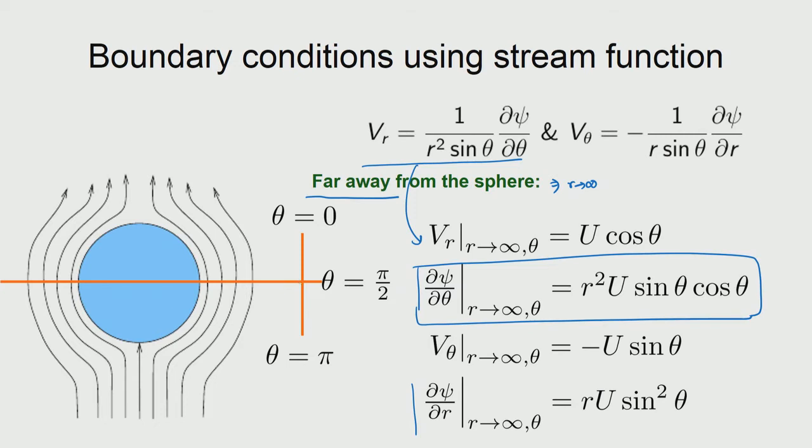You could actually see that the theta is varying in this manner. Okay. And we are actually looking at the vertical velocity, which means that at this point theta is 0. So, velocity is u, that will be coming up matching here, and below it should be minus u. So, cos of pi is -1, and that will be matching. At this position the velocity is 0 in the vertical direction, which also will come as u cos pi by 2 is 0.